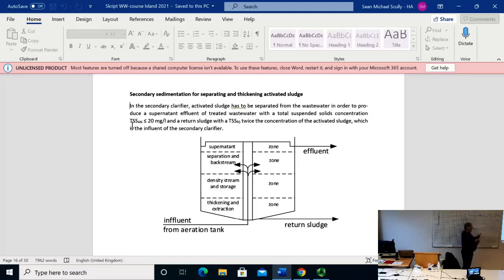And what comes out after dewatering, because after the anaerobic digester we dewater, and the solids that go out were 25% solids. At this point here, it is 5 liters per PE a day, and at this point it is 1 liter per person equivalent and day. Before, we have a pre-thickening here, mechanical thickening, and then we reduce this to 1 liter, so 4 liters go back.